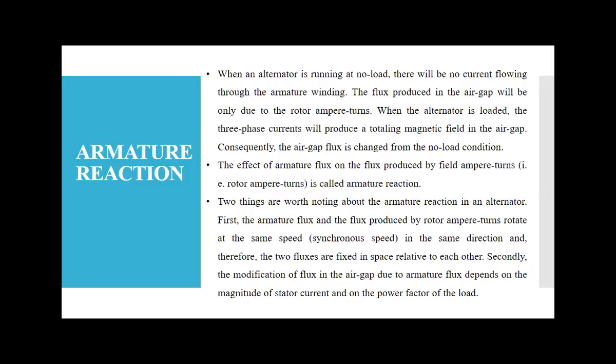But generally in that load, we have inductive nature and also capacitive nature. And there is winding, so there is some resistance also. So we generally have a load that is a combination of R, L and C. But whichever is dominant, according to that the power factor varies. Okay. If our load is more capacitive, then it will be leading. If our load is more inductive, then it will be lagging. And if my capacitive and inductive loads balance each other, then it will be resistive in nature. Okay, so that we will learn in today's session.